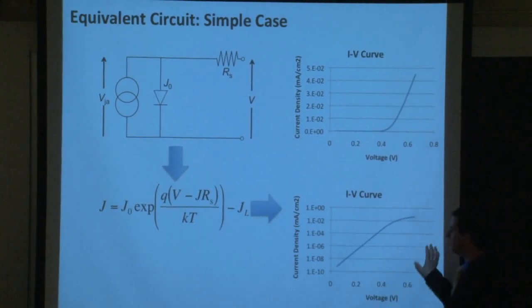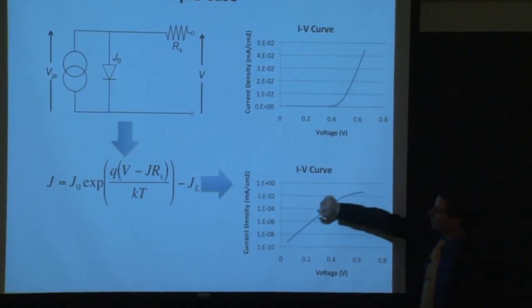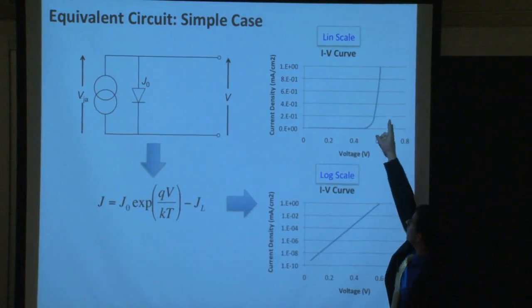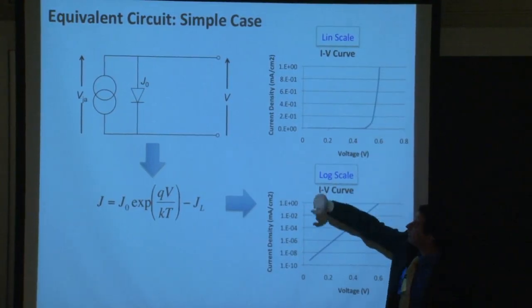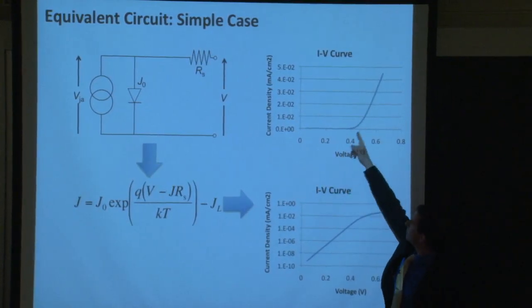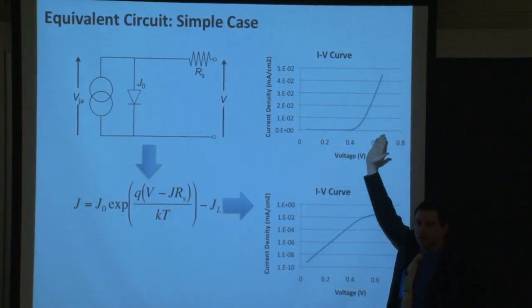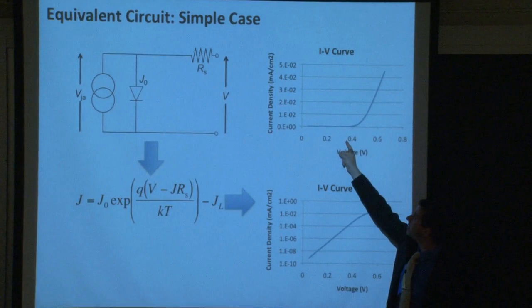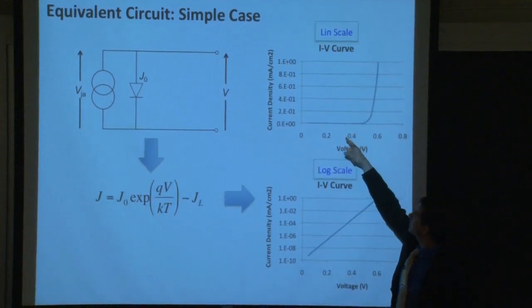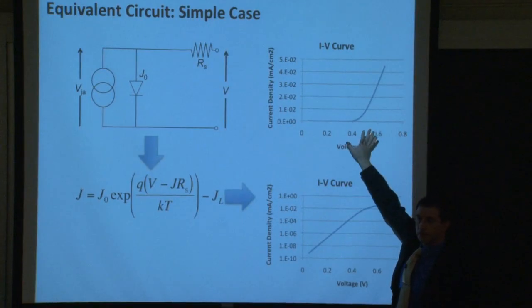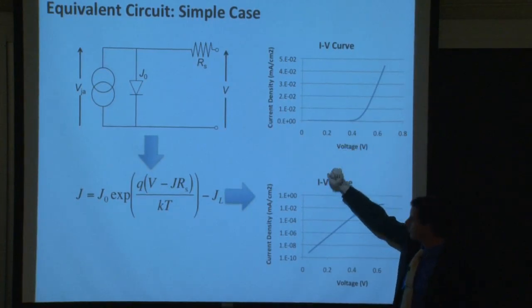And what is happening to our IV characteristics? Well, we'll go back once again to our ideal diode equation right here. We have a very sharp, box-like IV curve under the ideal conditions. Now when we introduce the series resistance component, we begin smoothing out that IV curve. The fill factor has dropped. Take a look. Ideal conditions, sharp, very large fill factor. Now we've added the series resistance component. The fill factor has begun dropping.